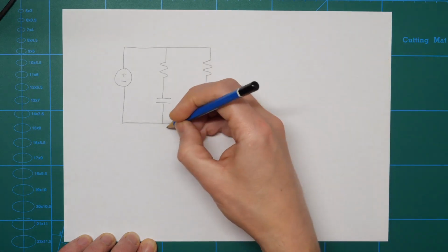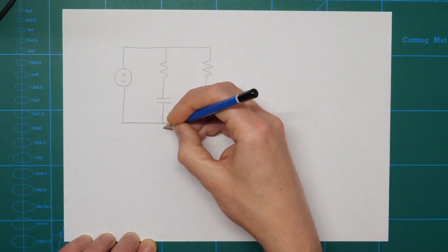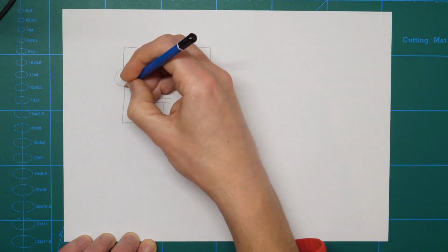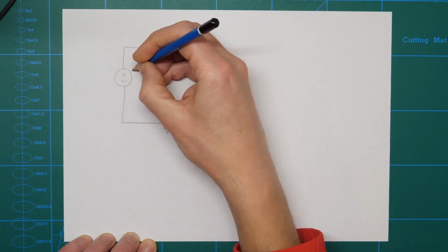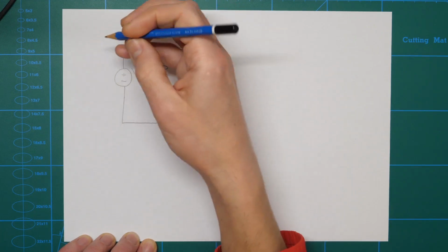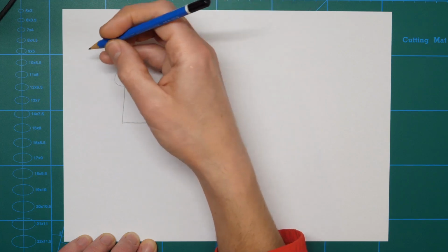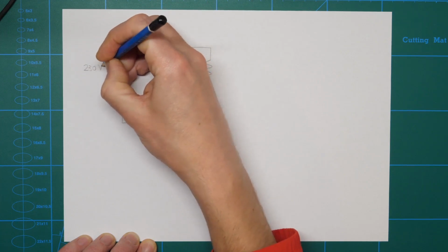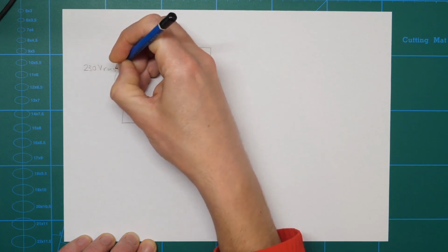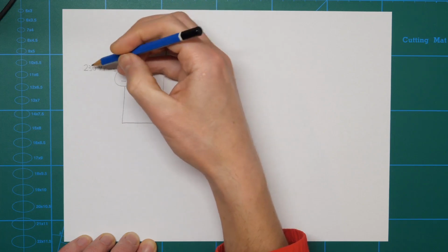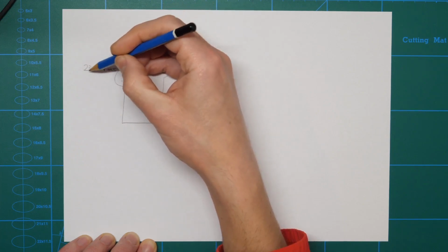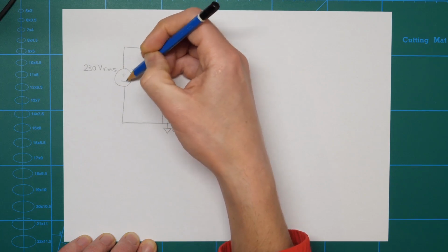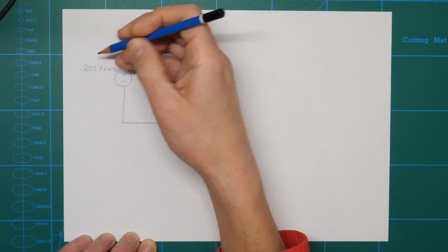When we simulate this in LTspice, we're going to explicitly ground this point here, so I might as well do that at this point. So this is going to be 0 volts in our circuit. This voltage supply here I'm going to call VS, and it's a sinusoidal AC supply. It's 230 volts RMS, so that's root mean square. The peak voltage out of this will actually be root 2 times this, but normally we would describe the amplitude of a sinusoidal AC source using the RMS value. So that's what I'm doing here.